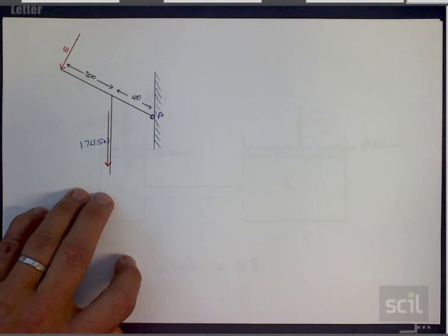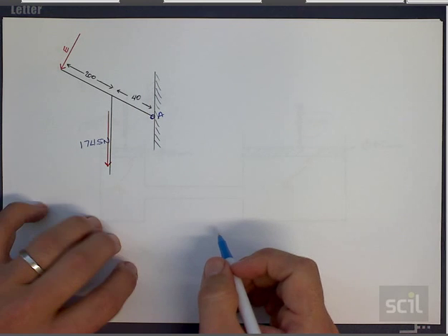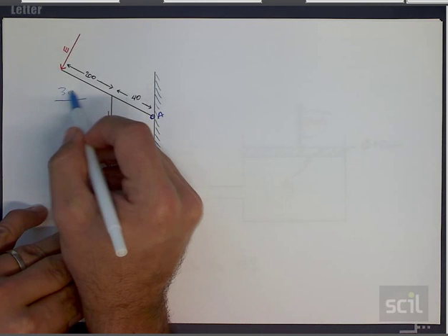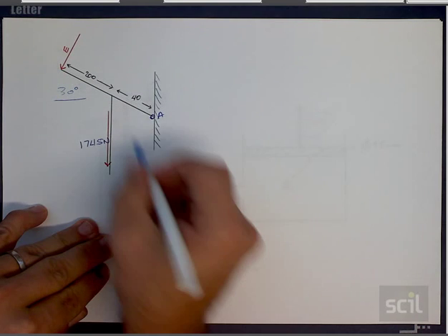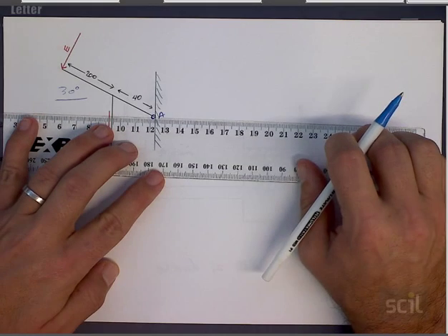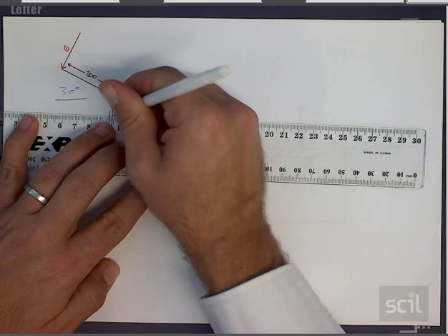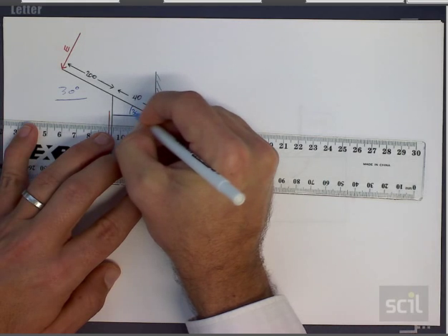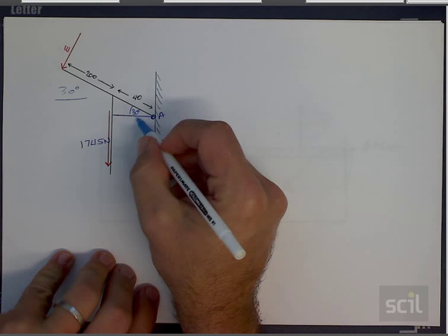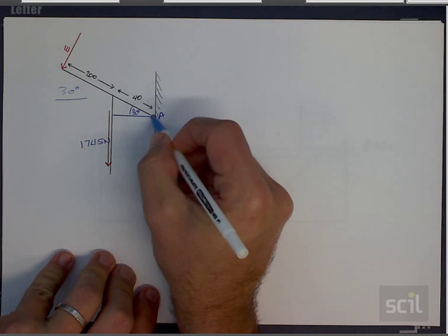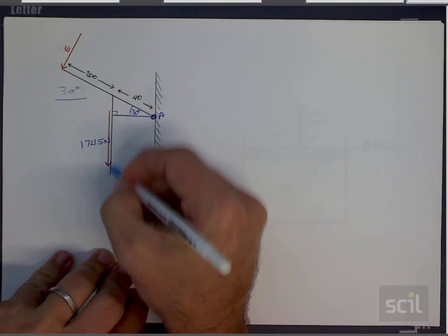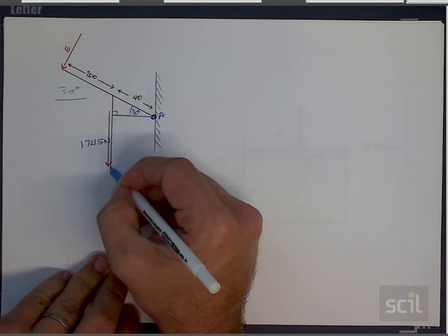And we need to now first of all make sure that we understand a couple of things. Firstly, we've been told this arm is at an angle of 30 degrees. Therefore, we can say that this line over here is at an angle of 30 degrees to this point here. If we understand our moment arms, we know that around a point at a perpendicular distance from a force, all the moments must add up to be 0.